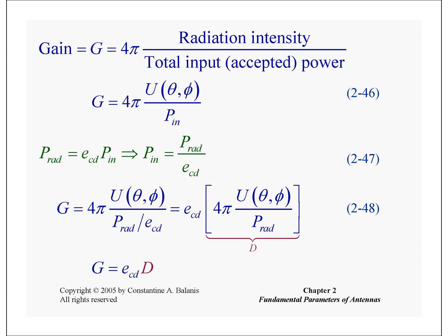Now the gain will be equal to directivity if the efficiency is 100%. If the radiation efficiency is 1, when there are no losses within the structure, then e will be 1 and G will be equal to D. However, practically G will be slightly less than D because nothing is lossless in this world. So gain can never be greater than the directivity, it will always be less than the directivity.